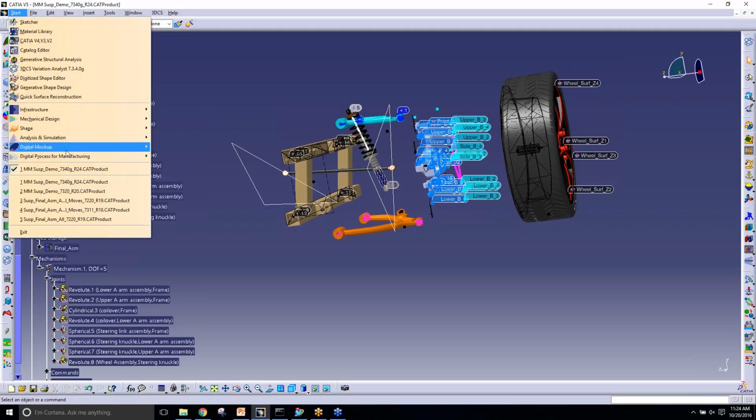from the DMU kinematic workbench. It's important to note here that because we are working now in kinematics, you do need to have the mechanical modeler add-on module for 3DCS in order to import these joints and constraints. The mechanical modeler is a really inexpensive add-on that gives you access to all these joints and constraints and the automatic extraction of them, as Jason's about to show, which will allow you to apply those as moves onto your model. So with the CATIA FT&A, the embedded GD&T in CAD, and with joints and constraints, you can have your moves and your tolerances drawn straight from your CAD system and automatically applied onto your model.